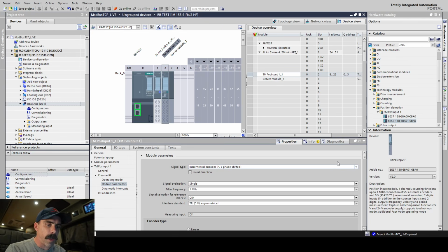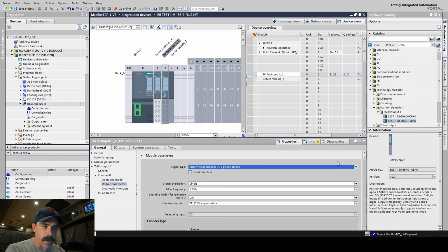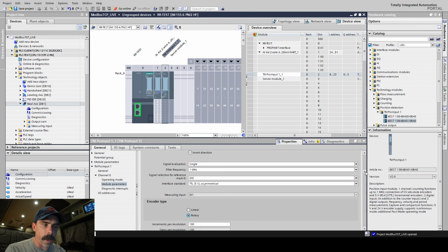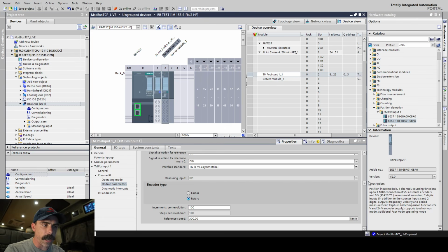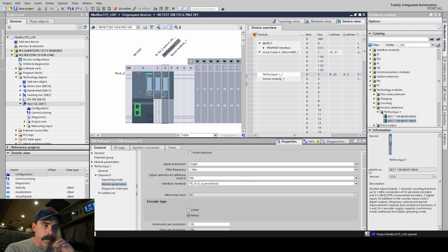So you're going to wire those up, and I'm not going to change anything here. There are a couple of different options that you'll have to figure out and play around with in order to get your pulses set up, whether it's a 1024 or a 2048 or 4096, whatever it would be, depending on how accurate your encoder is. That's what you're going to be setting up here.